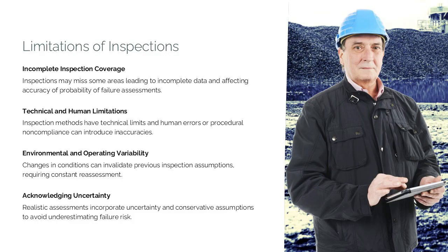Despite their importance, inspections have inherent limitations that can affect POF assessments. These include incomplete coverage, technical limitations of inspection methods, inappropriate technique selection, human error, and procedural non-compliance. Changes in operating or environmental conditions can also invalidate assumptions based on previous inspections.